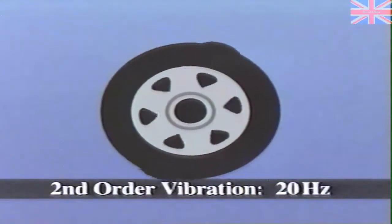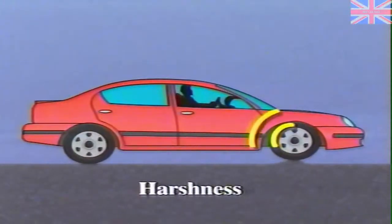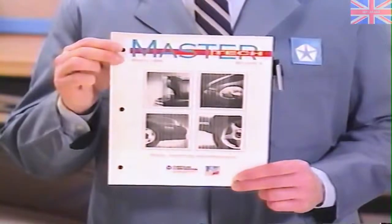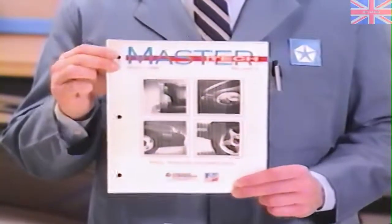of 20 hertz. Harshness can be considered a vibration that occurs as a shock when tires pass over road surface variations or road joints. Refer to this month's reference book to familiarize yourself with other important concepts like beat and resonance. Knowing the symptom's frequency is often vital when isolating trouble spots.